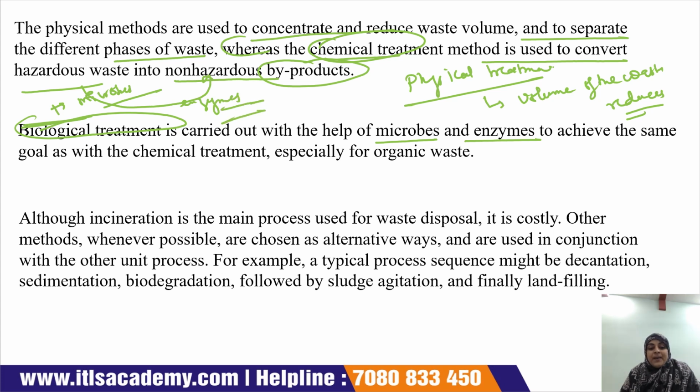So this biological treatment is carried out with the help of microbes and enzymes, so that we achieve the same goal as with chemical treatment, especially for organic waste. If we have organic waste, then in that case we especially use biological treatment for the conversion of hazardous waste into non-hazardous waste.